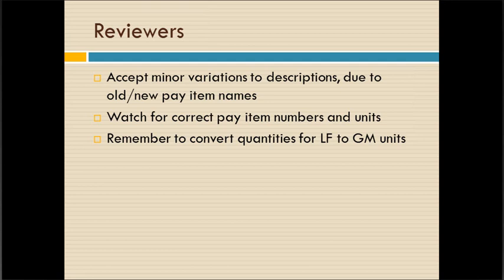We do want you to watch, though, that they're using the correct pay item numbers. Again, if they're talking thermoplastic, it's a 711 item. If you're talking tape, the permanent tape, it's a 713 item. Those are the things you want to really concentrate on.